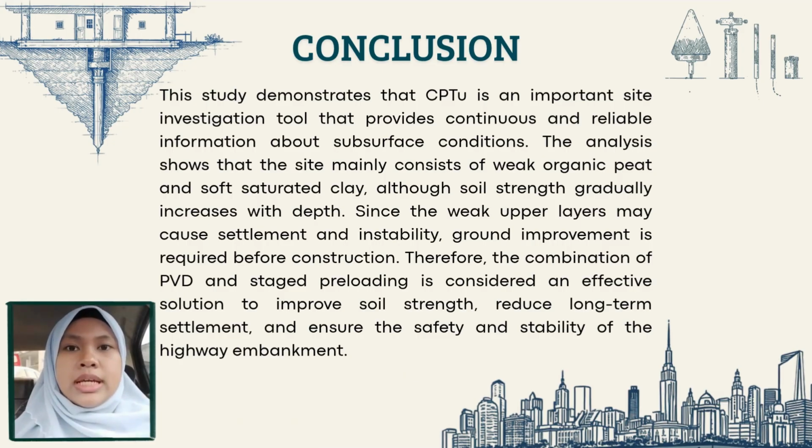In conclusion, this study highlights the importance of CPTU in geotechnical engineering because it provides continuous and reliable information that helps engineers understand the characteristics of subsurface soil. From the analysis, it was found that the site mainly consists of weak organic peat and soft clay layers with high compressibility and low strength. Although the soil properties improve with depth, the weak upper layers remain unsuitable for supporting heavy loads without proper treatment. Therefore, ground improvement is necessary to ensure that the highway embankment performs safely and effectively throughout its service life.